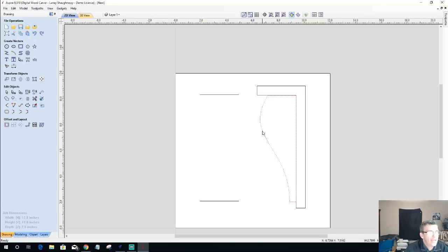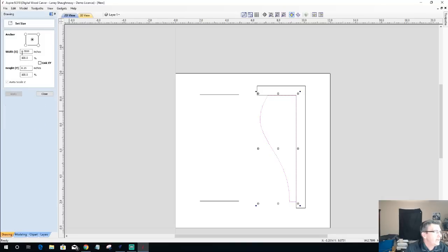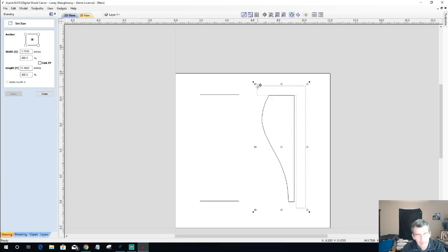So my key thing is in this height here, I want to be at that 2.5, and right now I'm at 2 3/4. So I'm a little overshot on my 2.5 inch thickness of my material. So I would end up getting an error saying that the model exceeds my material thickness. And so let's go ahead and reduce that down to about 2.5. Okay. And I can go ahead and get rid of this. I just wanted to draw that backer board in there.